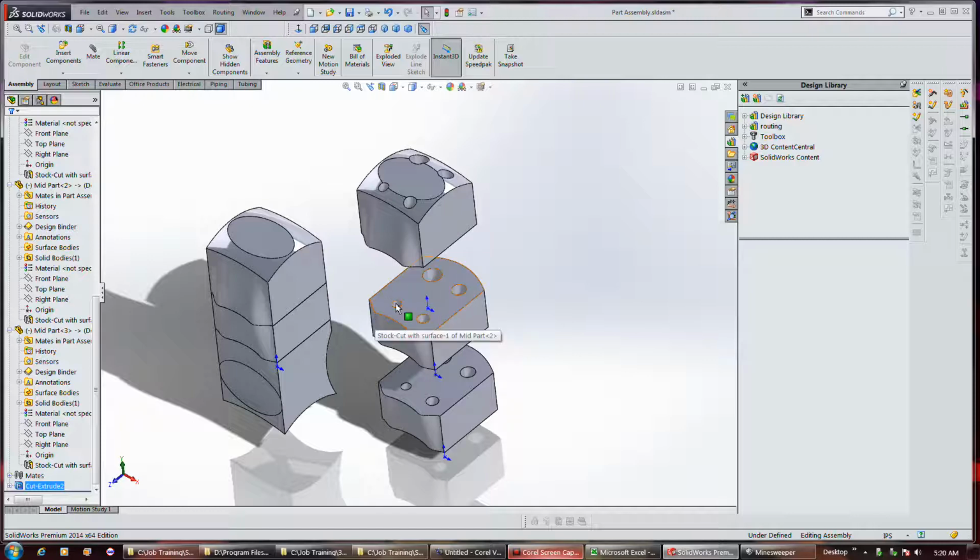So basically, that made a whole feature, and I could have extruded a square or anything through all these parts. But again, I think this is just within the context of the assembly. I'm not sure that it's modifying the original parts. I doubt that it is because we have copies of them here. So, you know, I don't see these holes on that. So, anyway, it's something to keep in mind. I'm not sure, like I said, if you make modifications on the assembly level, how you get them back to the part, because it's probably an important place to have them. So it's part of the actual original part, so you can send the part out to be manufactured and machined.